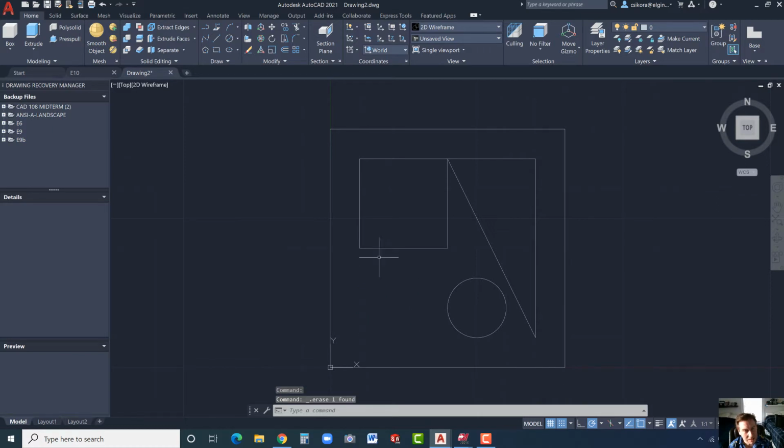Let's just delete that. And I'm going to turn off the snaps for a moment here. I think it's right about there, and this will be, we'll make the first one 0.25. And then go back to center diameter. And this next one up here will be 0.5.